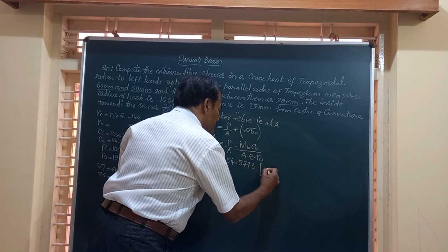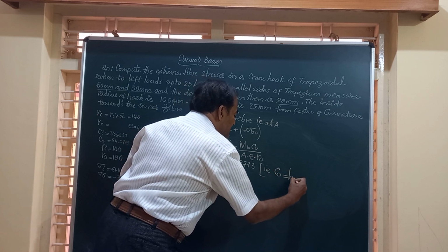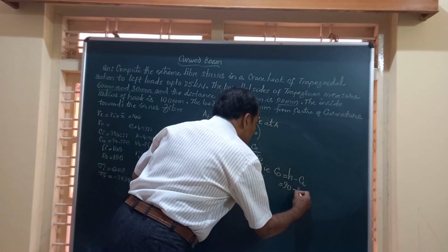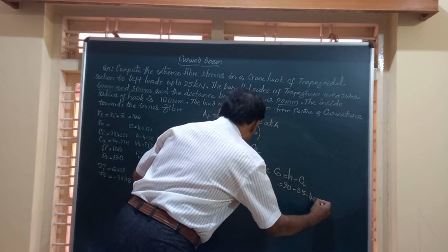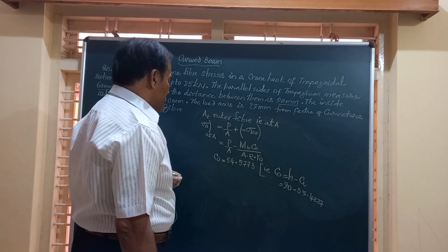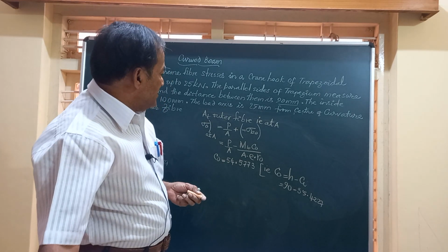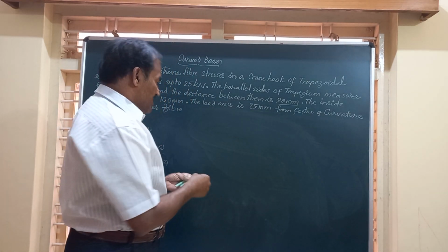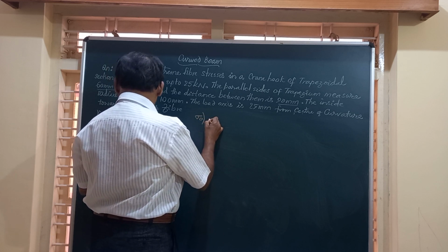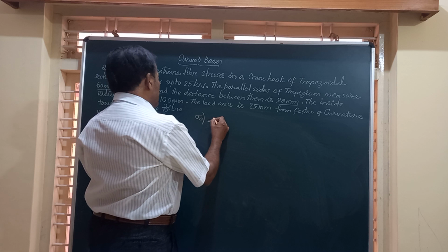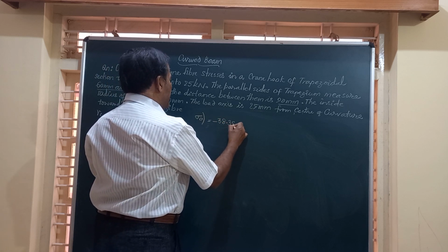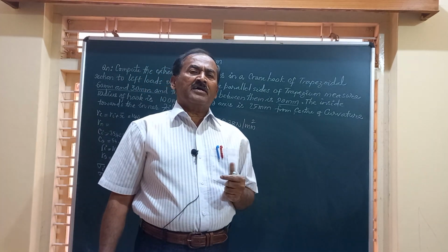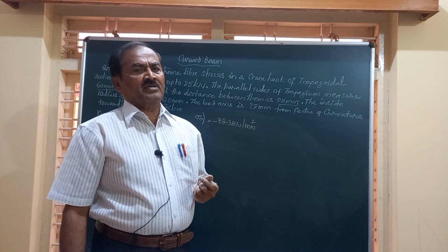Here, friends, CO is equal to H minus CI. H is 90 and CI value is 35.4227. And friends, this is the value you get. So we got the values of all these. Substitute in the formula and obtain the value of sigma O, stress at the outer fiber. Therefore, sigma O works out to minus 38.38 Newton per mm square. Friends, we are able to compute both sigma I and sigma O at the critical section of this crane hook of trapezoidal section.